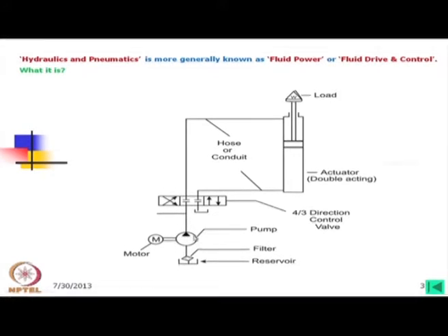then this pump which is pumping the oil will be pressurized and there might be an accident because this hose can burst due to the pressure. So, if the pressure rises above some limit, then oil should go back to the reservoir, and for that we add a pressure relief valve. What is pressure relief valve? We can set a pressure here, limit pressure, which might be equal to the system pressure, slightly above the system pressure. So, if there is any problem, then the oil will pass through the relief valve and it will go to the tank, and thus the safety is maintained.